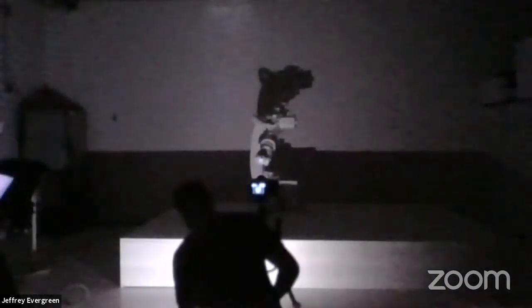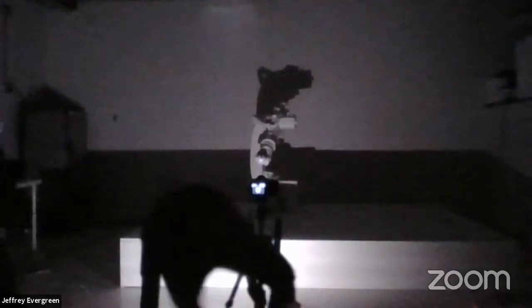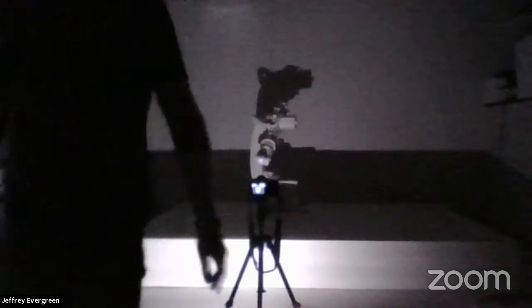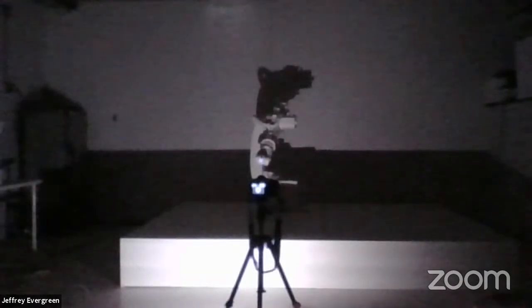What we can share though is how to set up the tool in the Teach Pendant in the robot, so that when you export the script, the robot recognizes the tool number, the rotations, and can find the values of X, Y, and Z, and the rotation that you were mentioning. So these things for sure, those are things that we can share with you guys.